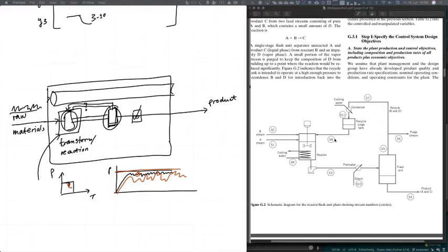So I don't know whether that's answered your question, but if the KPIs are chosen correctly, in other words, if the KPIs align with the control system design, and if we are truly interested in maximizing production of on-spec product, then we will operate the whole unit in such a way so that we minimize downtime, we minimize variance, we operate near the optimum conditions, and we have a control system that supports us in that goal. If any of those things don't happen, then the other things don't happen.